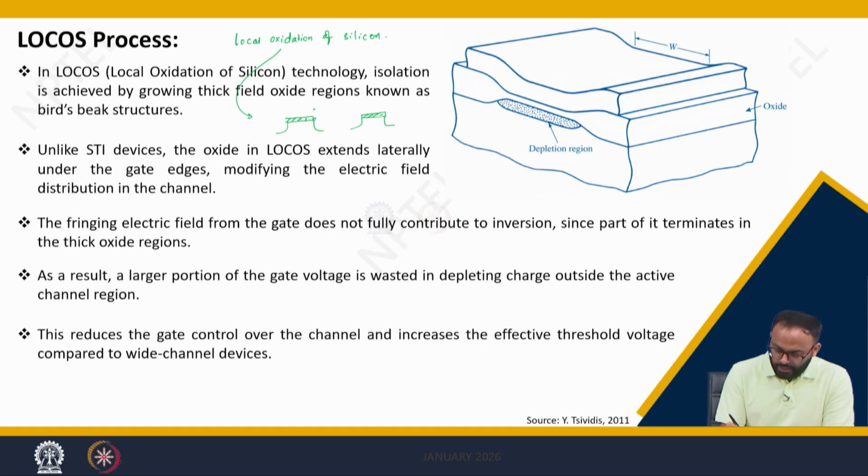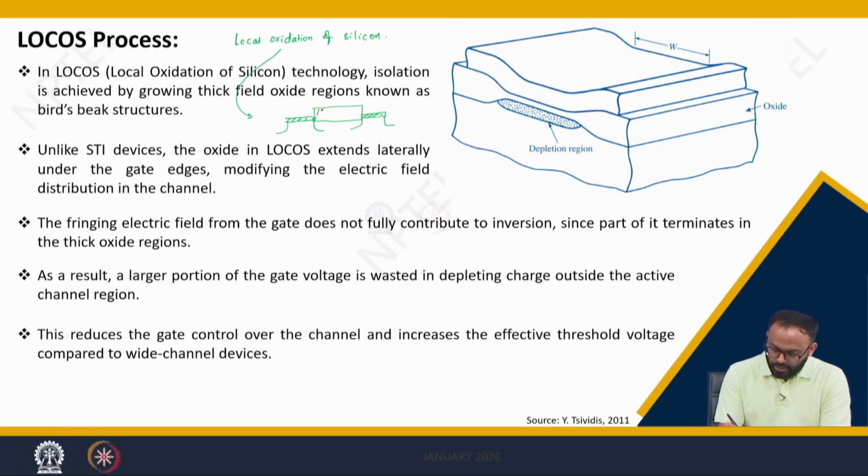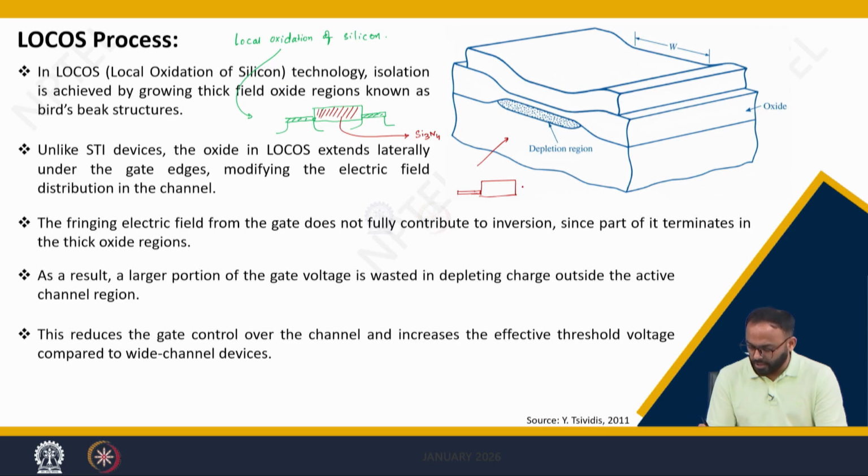So what we'll do is create an isolation thick oxide, right. So let me make it like this. So this is an isolation thick oxide, correct. In general, we can take some nitride layers such as Si3N4, right. So if you see from the width side, you will get this kind of structure. One is a gate oxide, one is an isolation spacer or isolation oxide, and another is the gate oxide